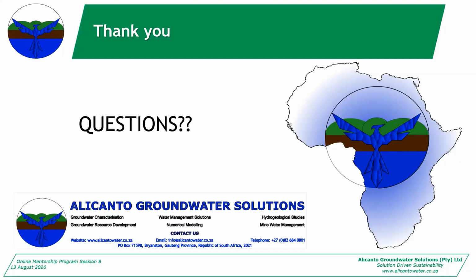Look, it's not going to add value, because an uncalibrated model is just going to give you nonsense results. It would be better to do a conceptual model before you do any numerical or analytical modeling. Your conceptual model will help you with your fieldwork design instead of your numerical or analytical model. So I would rather spend the time doing a conceptualization than running anything.